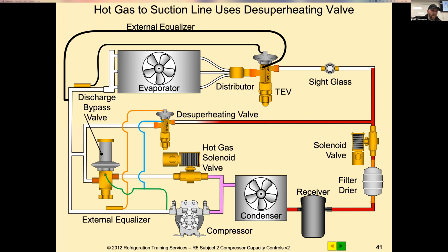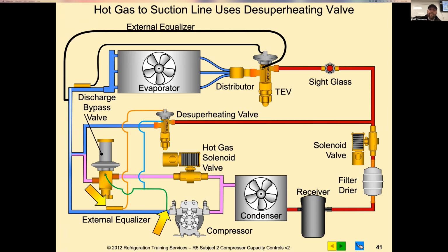So this is also bypassing discharge gas, but it's also using a desuperheating valve to mix that vapor to make sure it's getting more cool gas from the suction line. Or I'm sorry, from the liquid line into the suction line.